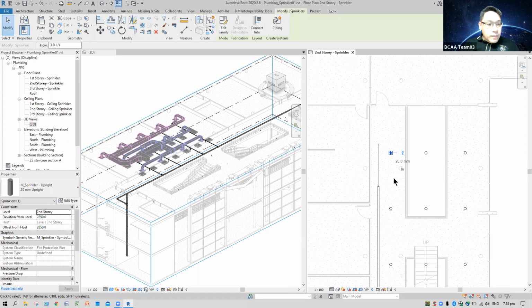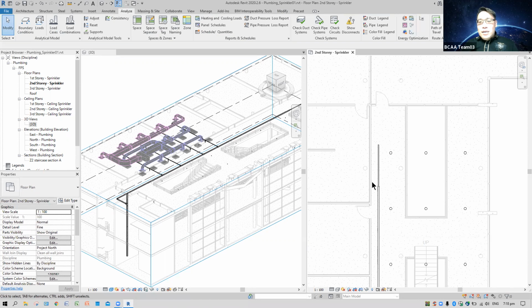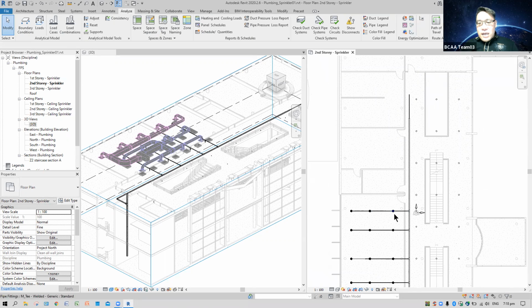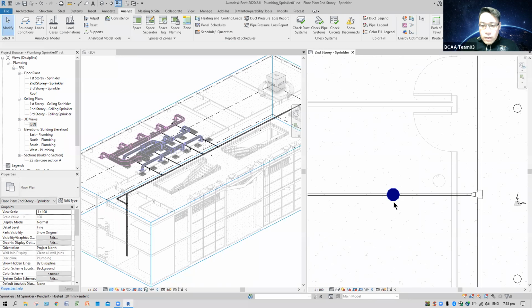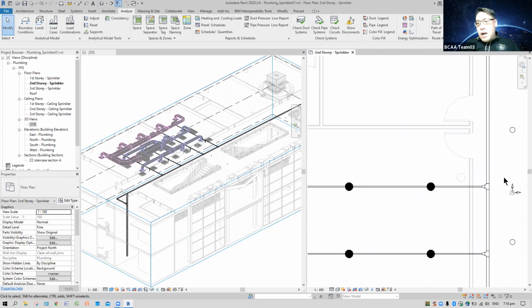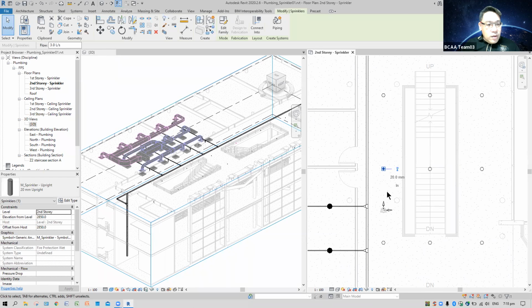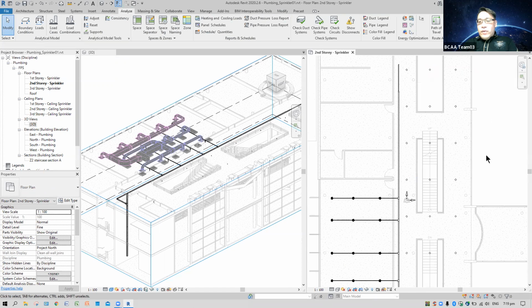What is this height? 2850? Wrong, no wonder no route. My goodness. Okay, lucky. The first one is at 26. All right, hold on. Your sprinkler at 26, right? How come this is at 2850? I made a silly mistake. It should not be 2850 because your floor to floor is 238. 2850 means that sprinkler might go out 1,000 above the ceiling. All wrong. Lucky we found out what's happening.